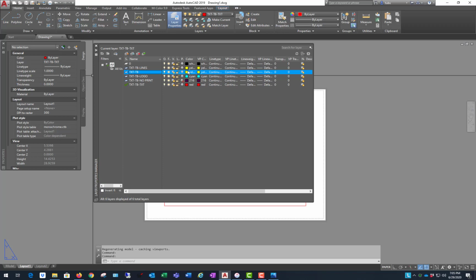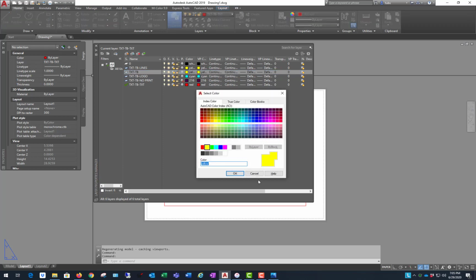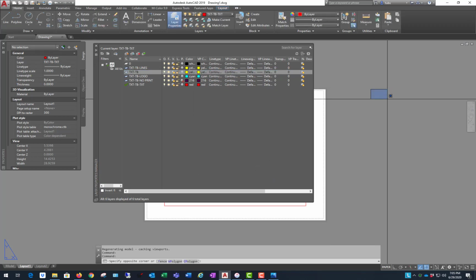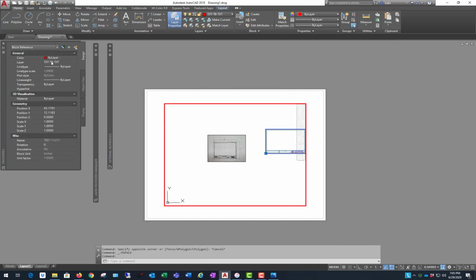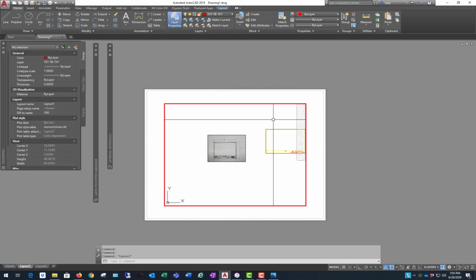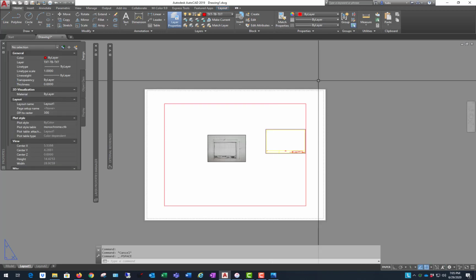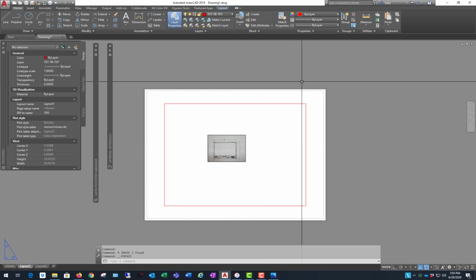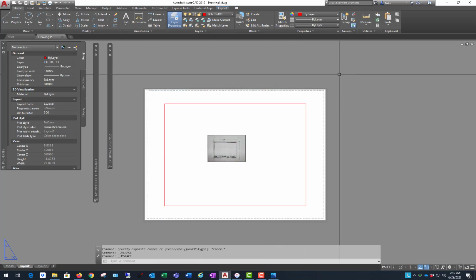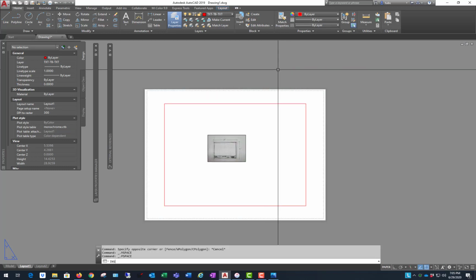The color won't matter because there's not anything drawn on this, but that's going to be the layer that my actual block is on. Right now it's on the text layer. So layers, use more, not fewer. I'm going to erase this, but it's still in my drawing because the block definition is still there. Anyway, let me insert my block now.